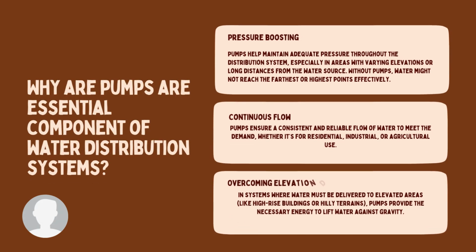So now, let's look into why pumps are essential components of water distribution systems. Firstly, for pressure boosting, pumps help maintain adequate pressure throughout the distribution system, especially in areas with varying elevation or long distance from the water source. Without pumps, water might not reach the farthest or highest point effectively.